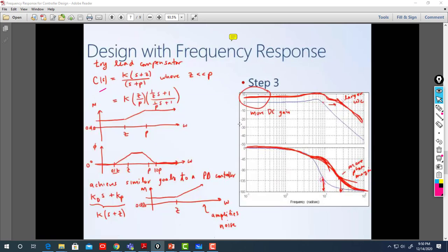So in this case, it seems like adding a lead compensator, which we know now how the shape of it looks like, which is equivalent to PD somehow, but PD with a filter, as we know. So then doing it, it seems like I can speed up a little bit. So at the end, I'm reshaping my system. Now we do an example in MATLAB to see how we design it. But simply know that I'm reshaping my system in this way, for example, to achieve my design requirement.